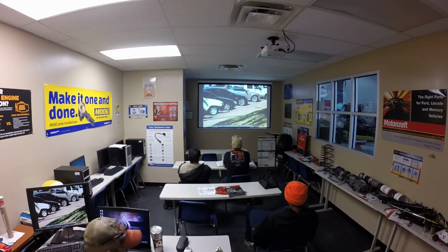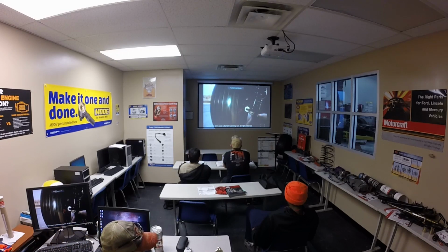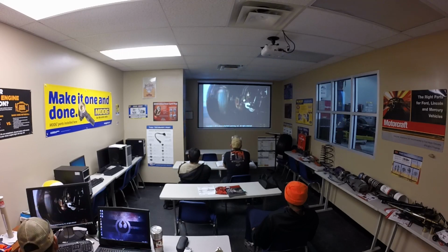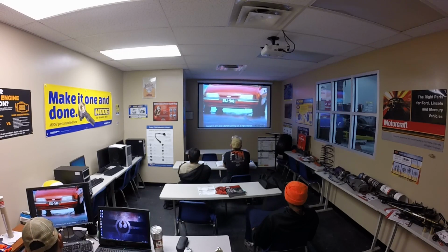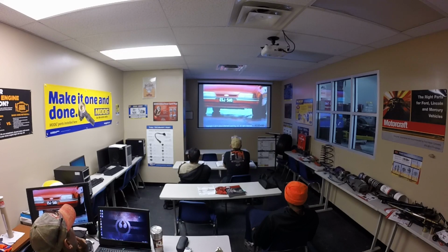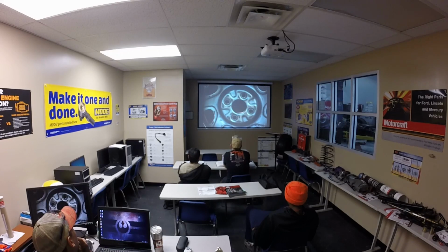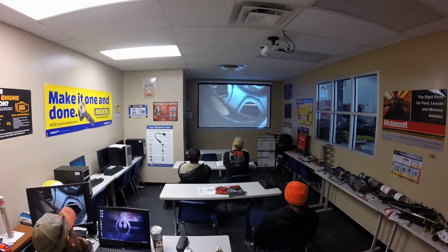Wheels must be strong enough to support the vehicle and withstand the forces caused by normal operation. At the same time, they must be as light as possible to help keep unsprung weight to a minimum. Wheels can be made from pressed steel in two sections: the flange or disc that is drilled for the wheel fasteners, and the rim.